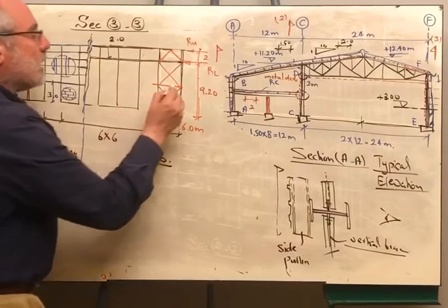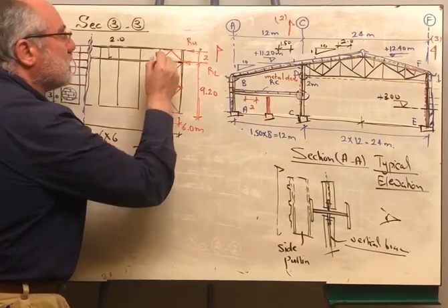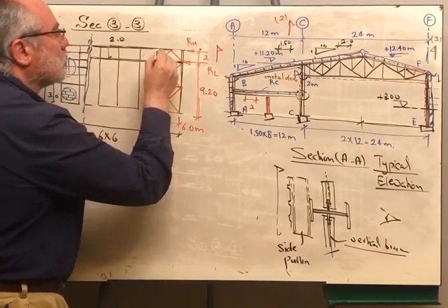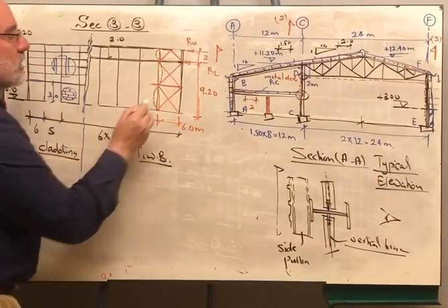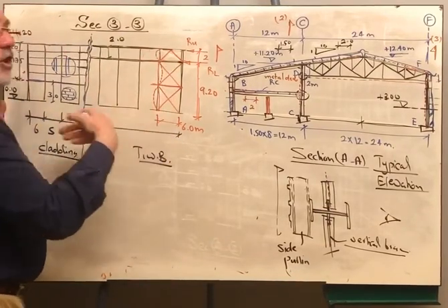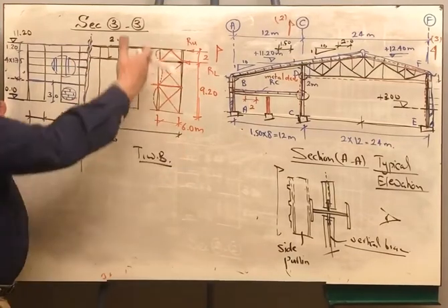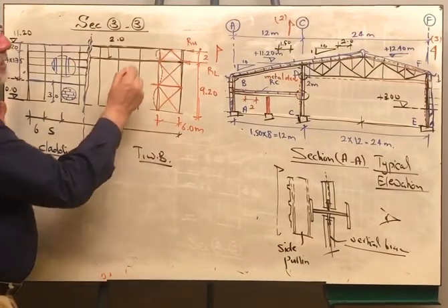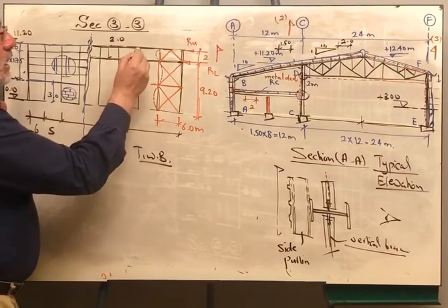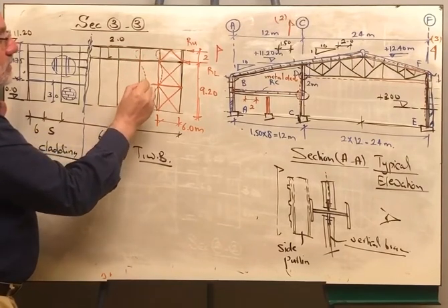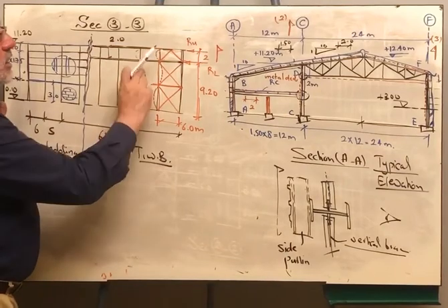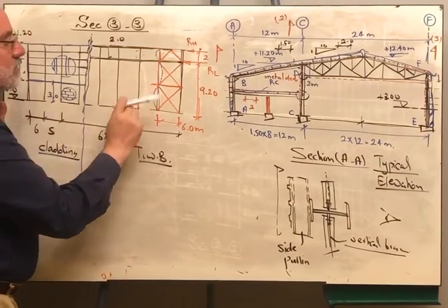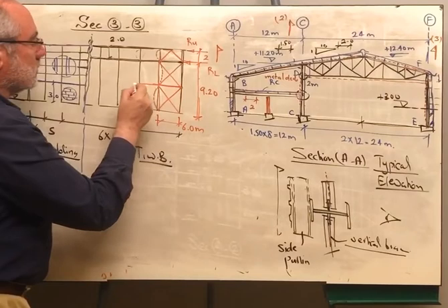Now, as long as you located a strut like this, this column, whenever it will buckle like that. Okay? So it is braced here. The strength of this column is very large. So you can reduce the size of this column. How about the column next to it? Now you are having a strut like this. It will be weaker because the buckling length here is bigger. I will have to extend the strut as usual.